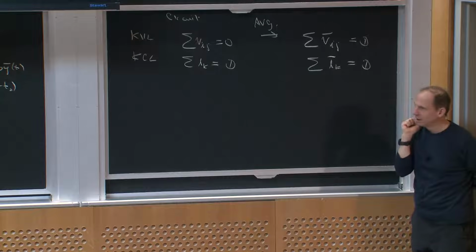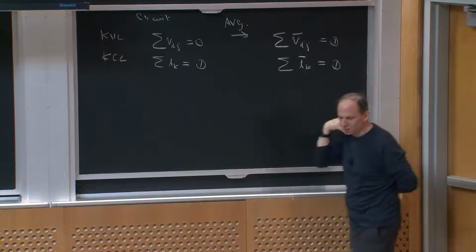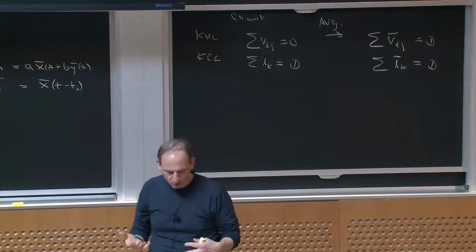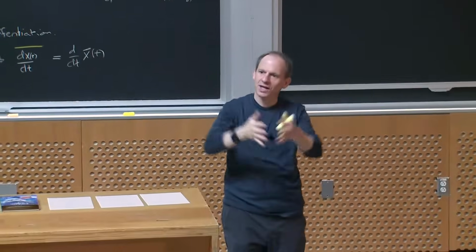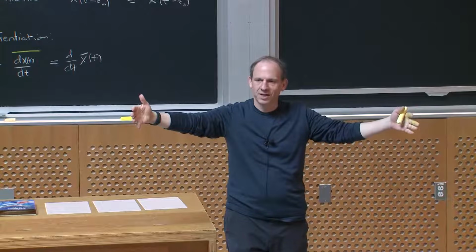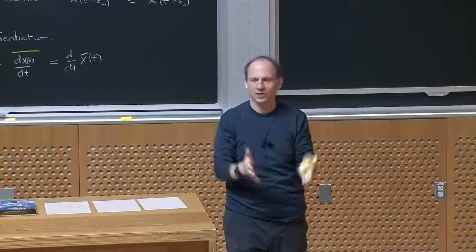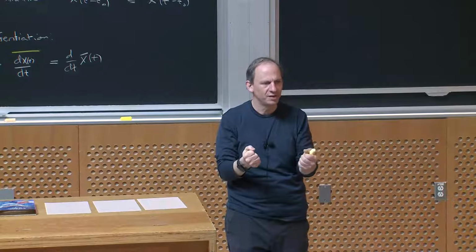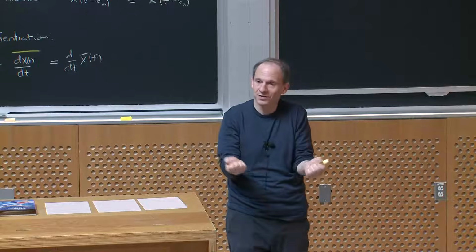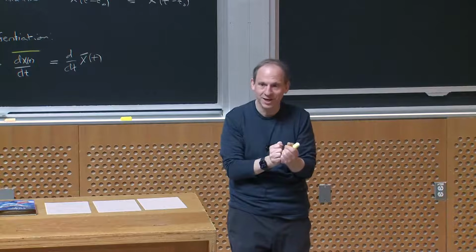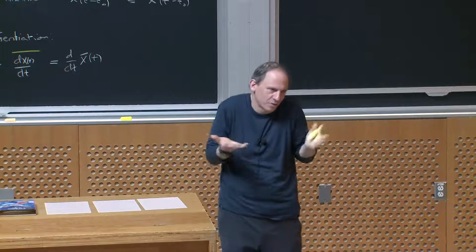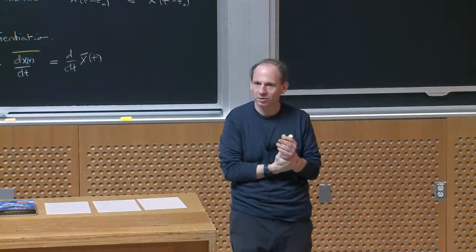Okay? Why does this work? This is similar to what we were saying. Remember we talked about average KVL and average KCL over all time, from periodic steady state. Well, I can also talk about it over a cycle, right? If KVL holds instantaneously, then it ought to hold for the local averages. And likewise, if KCL into a circuit node holds instantaneously, it ought to hold averaged over the last cycle. So it makes sense that you should be able to do this.